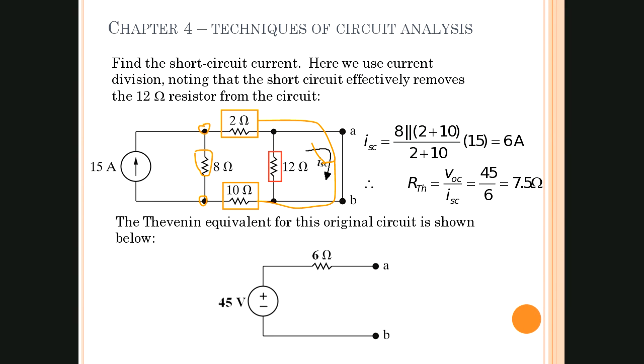And then when we got the 8 ohm resistor in parallel with this 12 ohm resistance, we get this equivalent resistance of 6 ohms. And no, we haven't done the whole thing yet. So basically what I've done is, and I'll see if I can redraw it right here, we have that current source, and we've done that equivalent resistance. I know this is not the greatest drawing. So I've now simplified that circuit, and basically you can do a lot of this in your head.